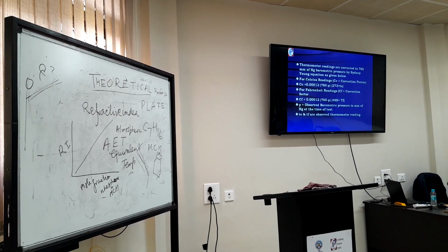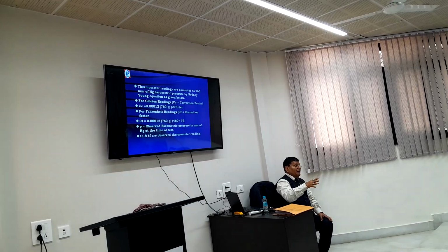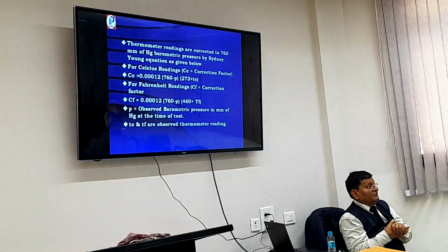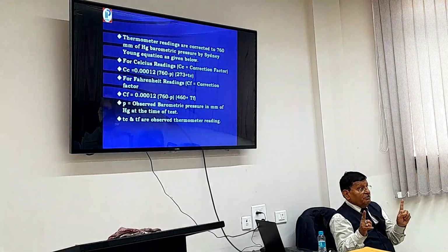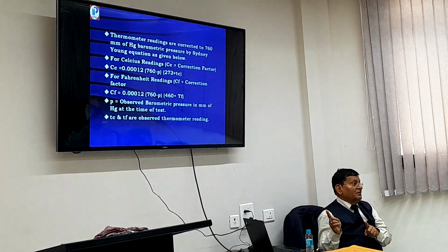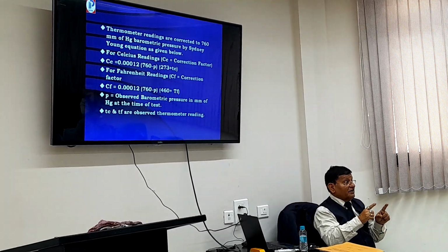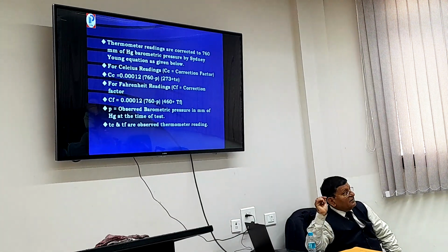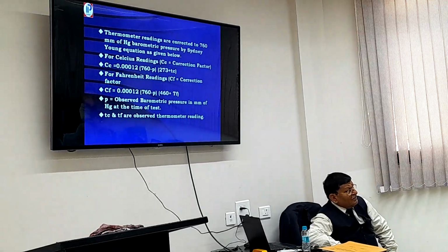In any report, when you are observing the data, you increase the flame height and then you get the final boiling point. The total time of the distillation comes to 30 minutes. This is a manual distillation. When there is a controversy between the results of two countries, only then is this the referee method. If the results of two countries from automatic or semi-automatic instruments do not match, then one has to convert using this manual method, so it is the referee method.